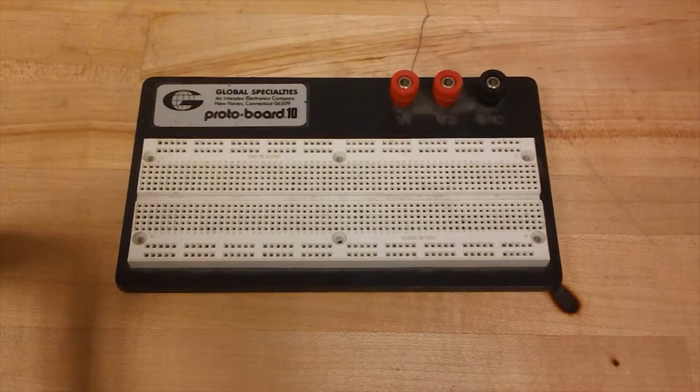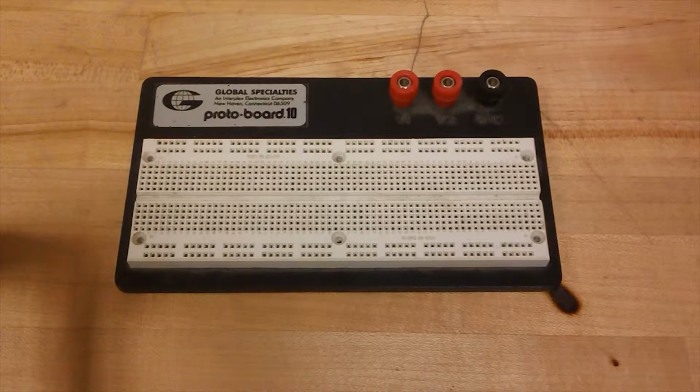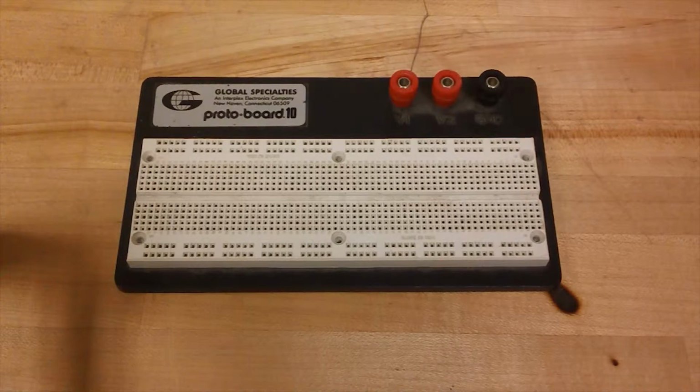A breadboard is a base for building temporary or prototype electronics. The breadboard is separated into different areas. How a breadboard is connected is important to understand. The columns of connection points seen on the left of the breadboard are connected vertically and will have the same voltage all the way down the column. The connection points in the middle of the breadboard are connected in rows of 5.